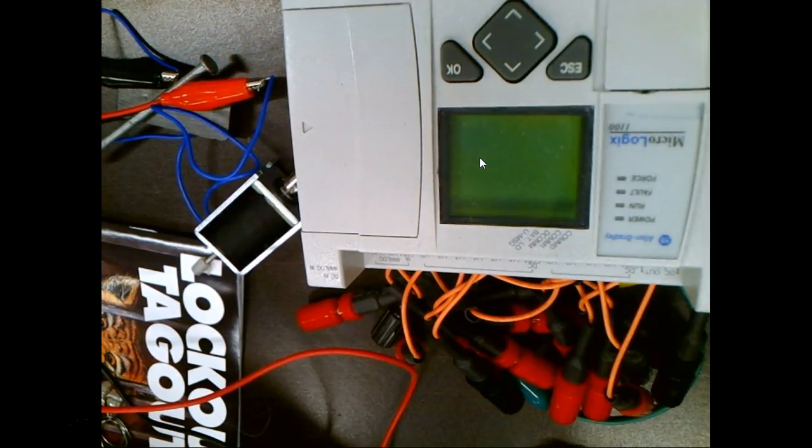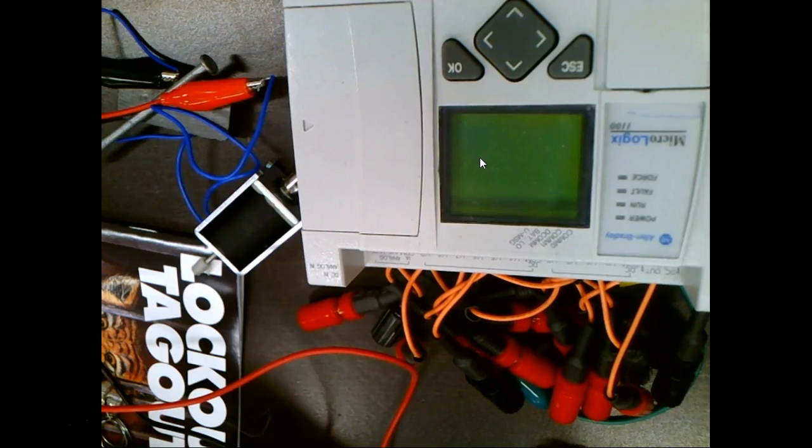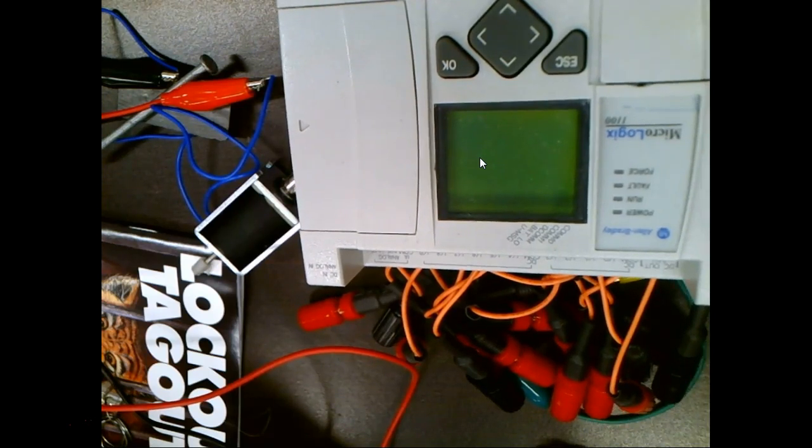So this light switch over here would switch 120 volts DC just like it would switch 120 volts AC, right? You understand? The contacts don't care what type of voltage or current you put on them. All they care about is how much voltage you put across them, right? So what's nice about having relays on a PLC is that I can run AC devices on one output and DC devices on the one next to it, because we're controlling contacts.